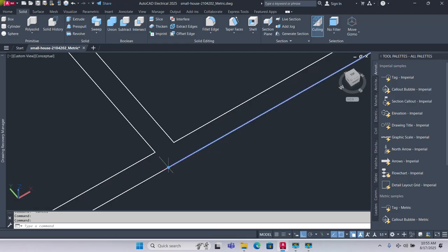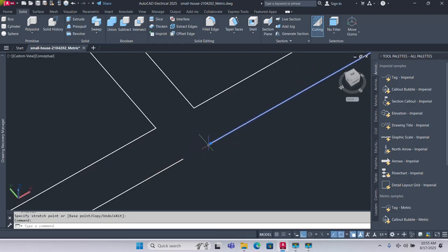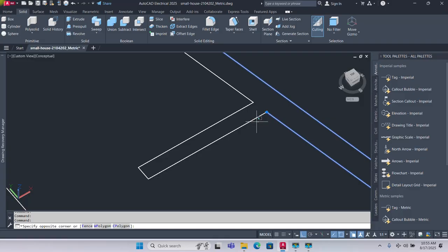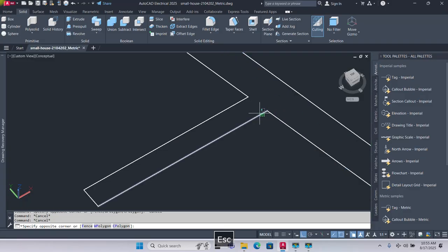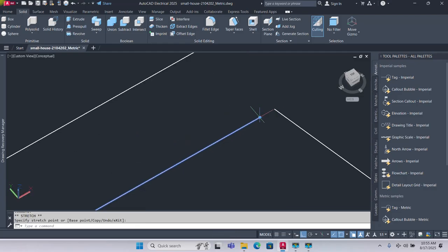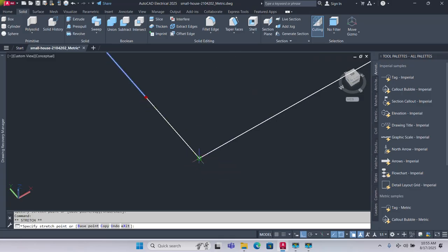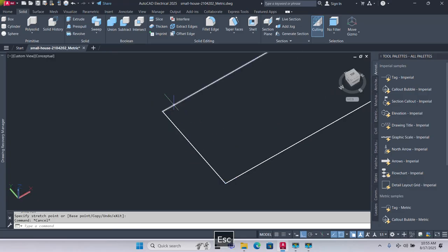So this line is not joining. I will just come here, join it to that endpoint, select them, J for join. This should now be one object. And we'll continue working our way that way till we finish up all this. And let's see this as well. This is not joined, so I'll move this out first, move it back to that endpoint. I don't want any other thing other than endpoint. Escape, move this out, move it back till I see endpoint.